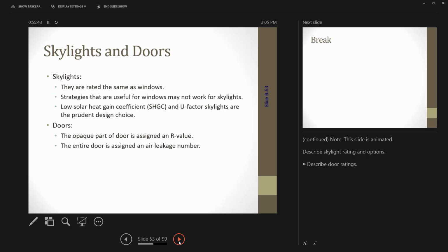So obviously if we go in the house that we're going to work on, we hopefully try to get 2 houses, but it's about 20, maybe not, 18 years old, and so the windows that were used were at the time probably windows that met code. They're probably a U value of about 0.4, maybe 0.42. Probably if we look at straight energy gain, if we went in and replaced all the windows, it would probably give us the largest decrease in energy usage. But I think we'll find a bunch more other cost-effective ways to improve it.